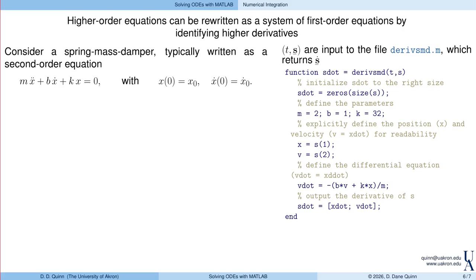Typically, we deal with higher order equations, right? So second order equations, third order equations, multiple degrees of freedom. Well, MATLAB really only takes in systems of first order equations. But fortunately, we can write higher order equations as a system of first order equations by identifying higher derivatives, right? So let's look at that spring mass damper system that we had at the very beginning.